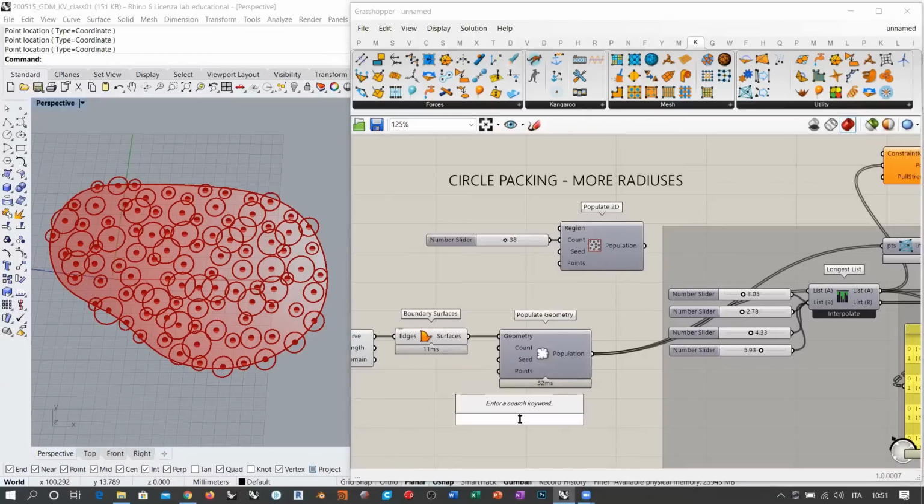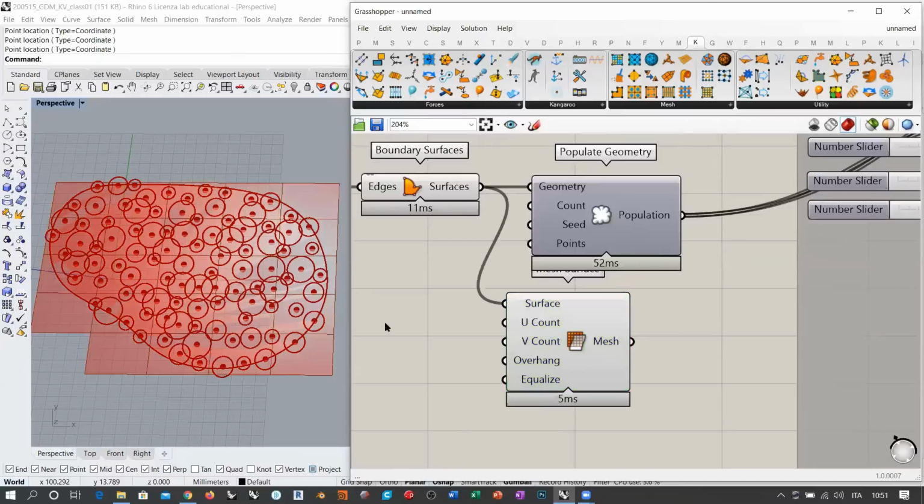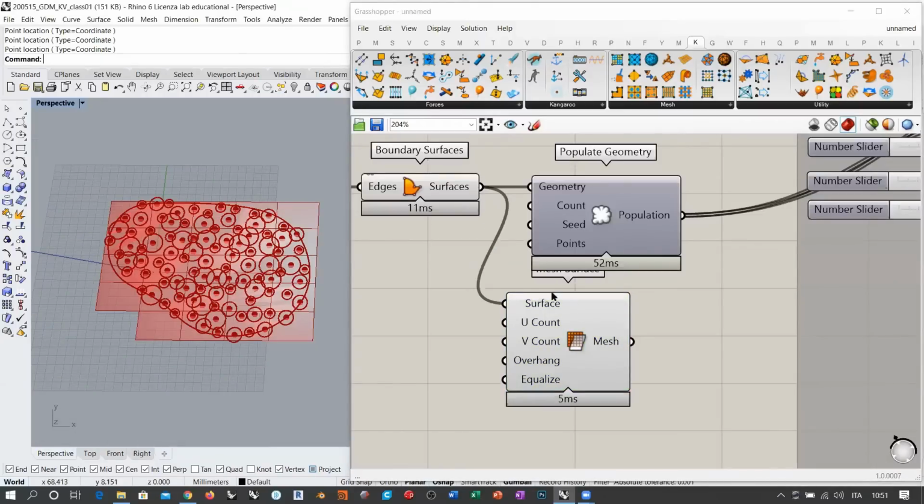So if you try, for example, to mesh surface this thing, you will get this. According to the resolution that you give to this object, you have this segmentation, these faces that come up, which are the polygons of your mesh. And if the polygon intersects the surface, it is kept. If it doesn't intersect the surface, Grasshopper doesn't consider it. Okay.